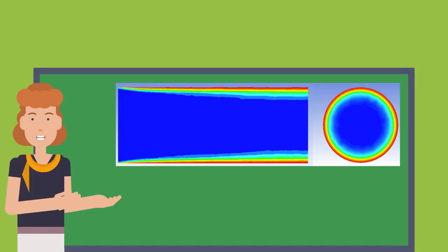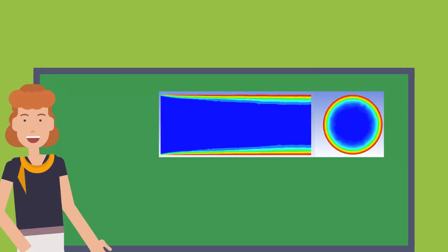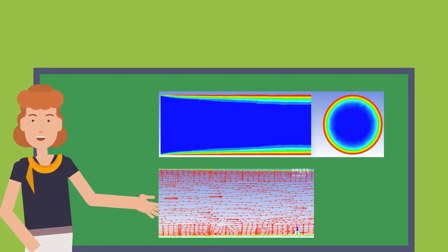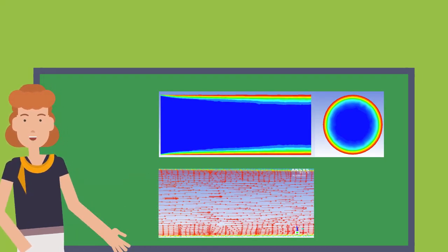In this figure, you can see a simulation made with ANSYS Fluent. It represents the wall of a circular duct that is hotter than the fluid circulating inside it. You can see in the color map how the fluid closest to the wall is hotter than the one in the center of the duct. Moreover, you can see how this disturbed area increases its thickness along the pipe. Fluid velocities are represented in this new figure, showing lower velocities for the fluid close to the pipe wall.